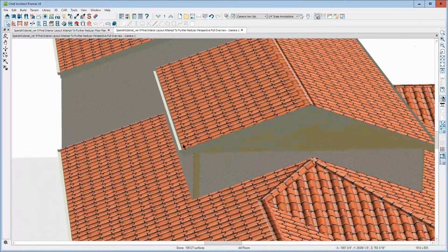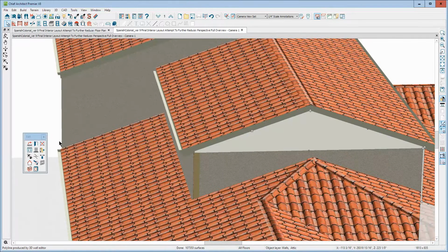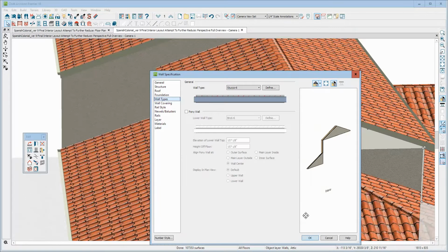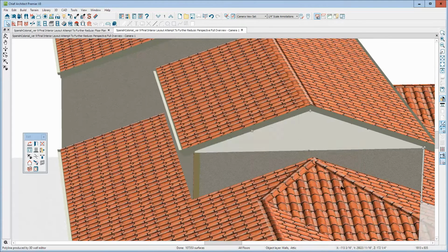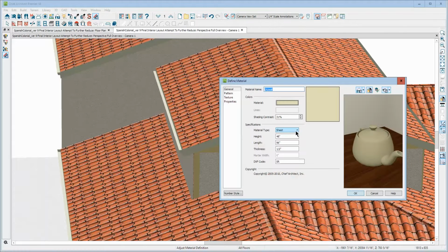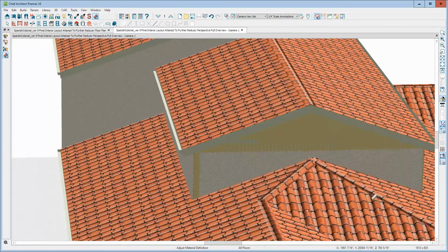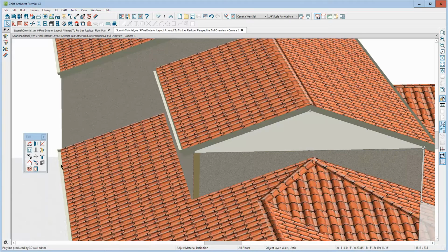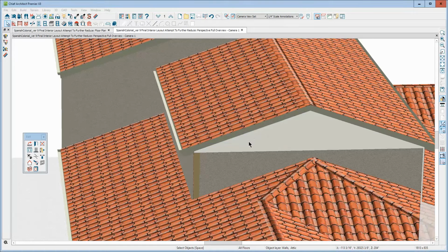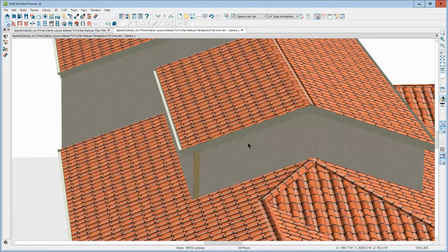Looks like this is the wrong material. Let me check that. You check the wall type on it. Stucco 6 doesn't look like Stucco 6. Hey, look, what is that material? It's drywall. Okay, so this wall's facing the wrong way. I'm going to flip the layers using this tool right here. Software is saying, hey, it's an automatic, but that's what was indicated.